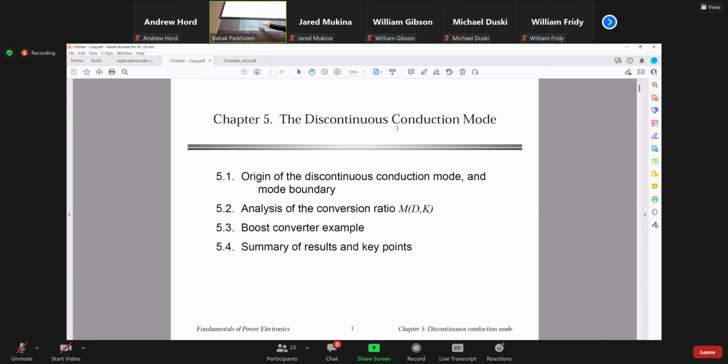Again, same switches, same symbols, give you different characteristics. So now this is like a third version of this circuit. The first version, how we derived it from electronics to power electronics, we got the simple D: the conversion ratio of the buck converter is D. Then we included non-idealities, and you saw that it's not D anymore, it depends on the resistances, so you have a more complex relationship.